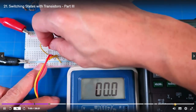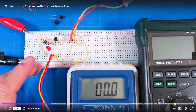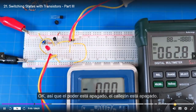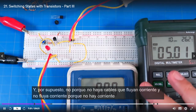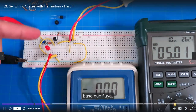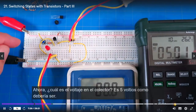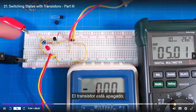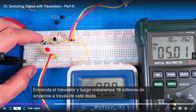Okay, so the power is off, the LED is off. I'm going to turn the power on. Should the LED turn on? Yes or no? And it didn't. Of course not, because there's no current flowing. Why is there no current flowing? Because there's no base current flowing. If there's no base current flowing, then there's no collector emitter current flowing. Now, what's the voltage on the collector? It's 5 volts as it should be. The transistor is off. Let's turn the transistor on, and then we're going to dump 16 milliamps down through this diode. Ready?